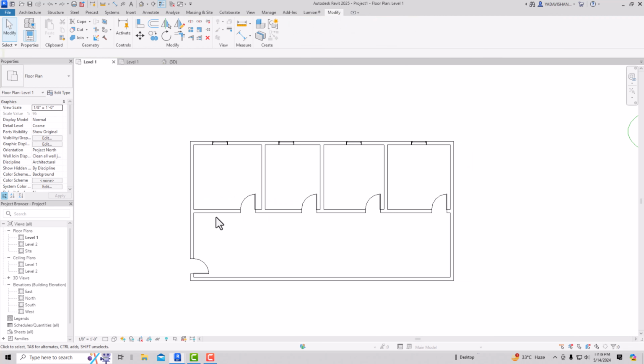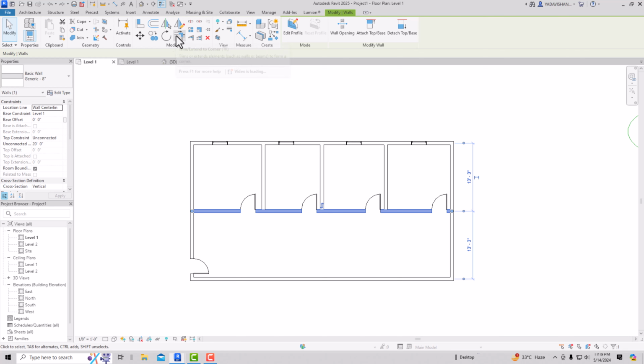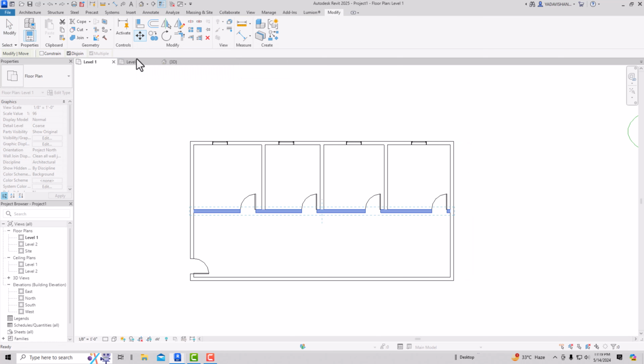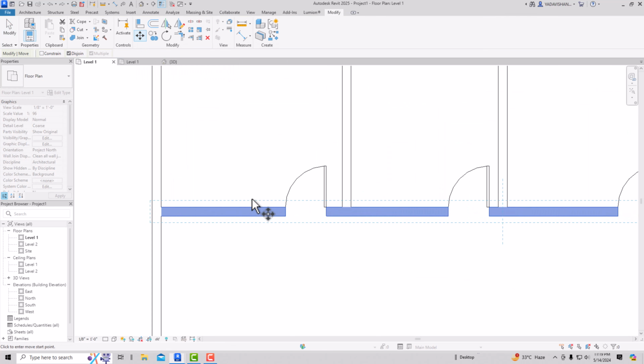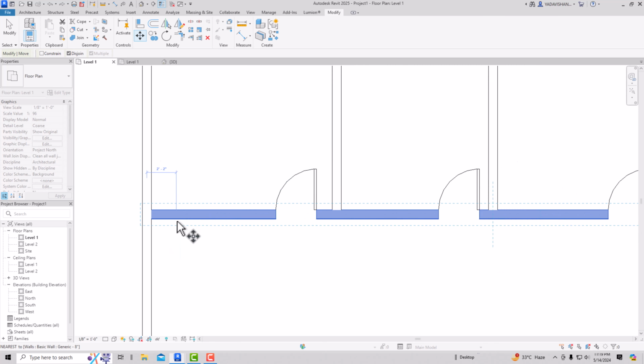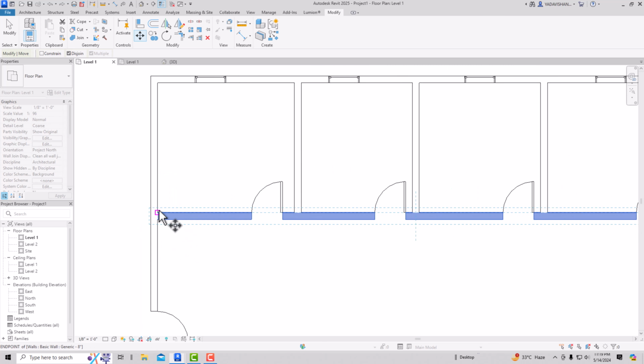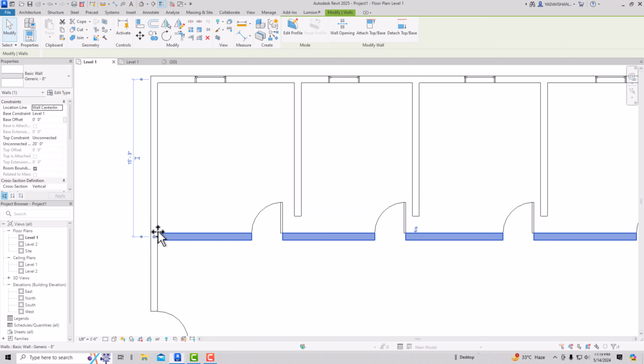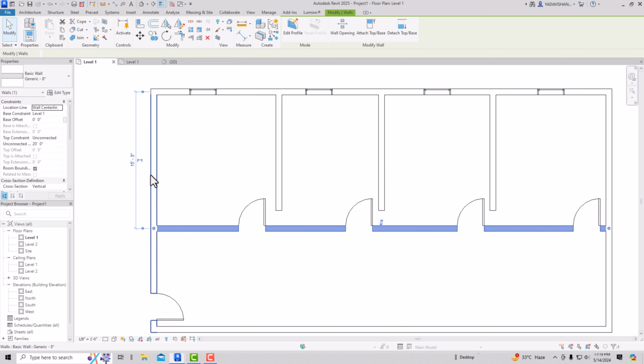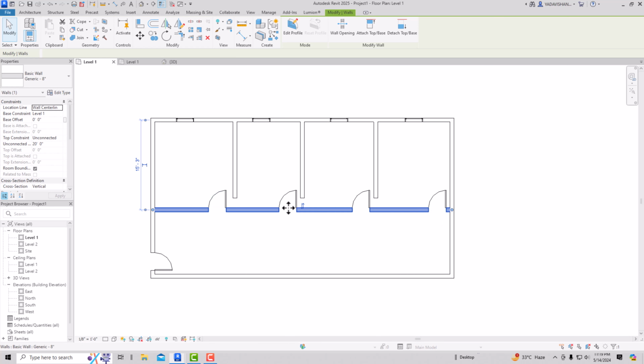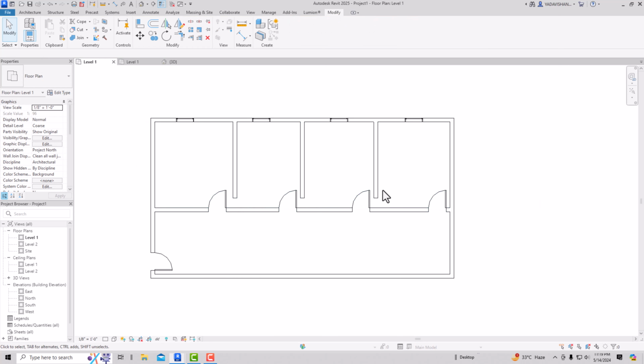Likewise, again you can select this wall and select the move tool or type MB. You can see this dash line here. That means this is selected and ready to be moved. So again I'm going to move it forward 2 feet. You can see the whole area is moved here, the whole wall is moved along with the door. You can see this wall is not extended.